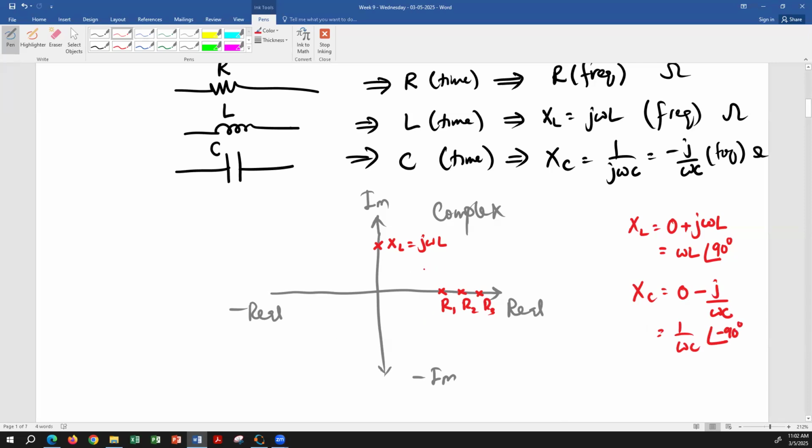Now, any number, any voltage, any current that is given in one of the four quadrants, if it is given in rectangular form, you will have to convert that into polar form. Not for the sake of multiplication or division, but if you're giving a final result, remember in the time domain you need the peak value and the phase. Now, your calculations are usually done in rectangular form. MATLAB cannot do polar multiplication, so polar numbers always have to be converted into rectangular form, and then MATLAB can manipulate them.